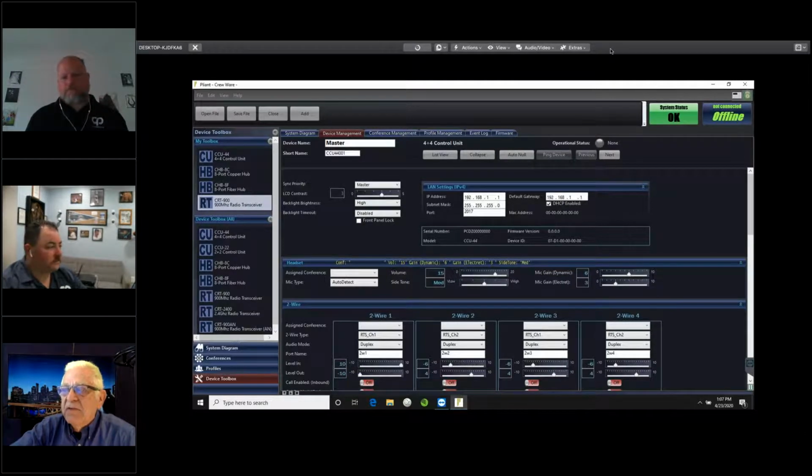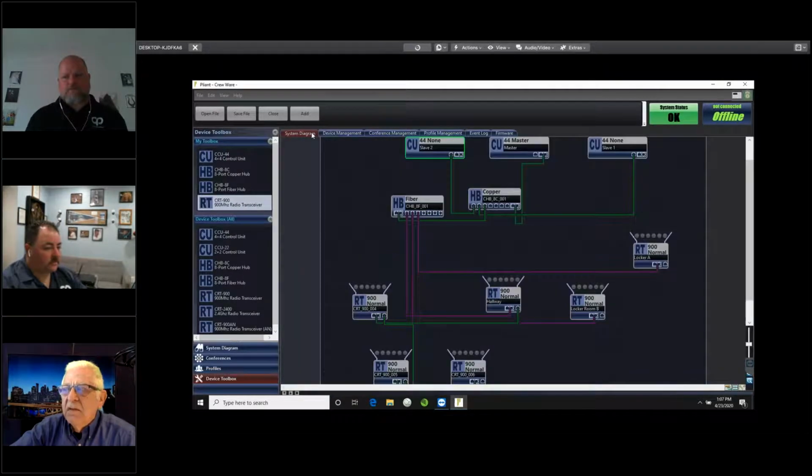Same on a ClearCom 2 channel, I think. That's a good question, because normal ClearCom channel 1 comes in on pin 3. Does a TW switch it? No, I don't think it does. I think it just adds the other channel. So I think the channel numbering in ClearCom is the opposite of the channel numbering in RTS.